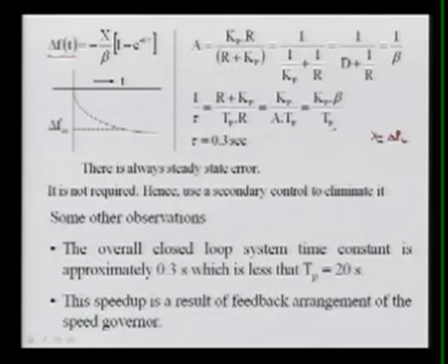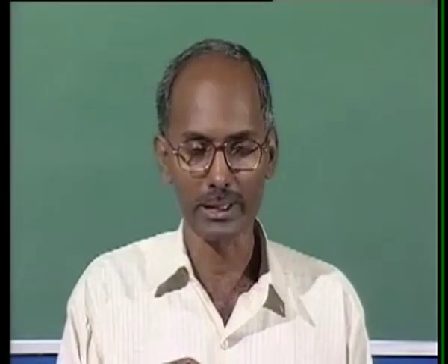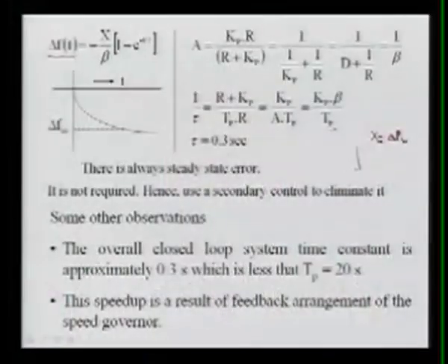If your load is gradually changing, then what will happen? The load will be met by the governing system as well as the net load release, and the frequency error will not be maximum. But here we have assumed a sudden change in PL, and this is called the step response.